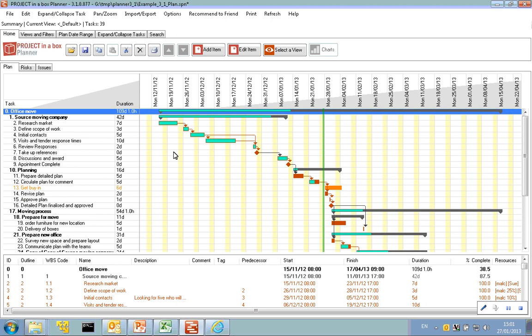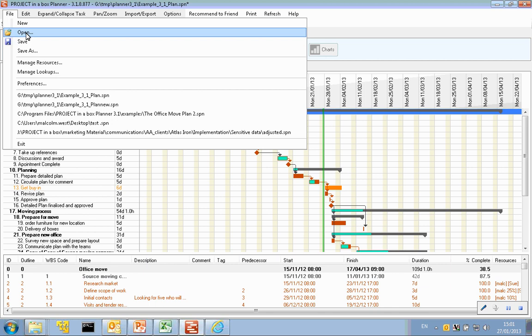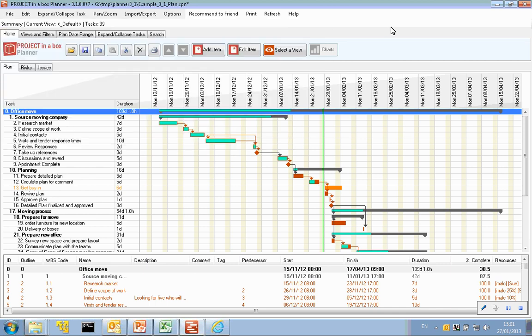Okay, so we've just clicked on a .spn file, maybe in the main application to check it out or view it, or a file that somebody sent us separately, and it should then naturally open in the Planner application. That's because it's using file associations to open files with a .spn type in Planner. Now it is possible that that doesn't open, because the file association might not be set, in which case you can come to File and use the Open form to browse to your file and open it directly from Planner instead. If that's the case, you can reset the file associations using the Planner installer.